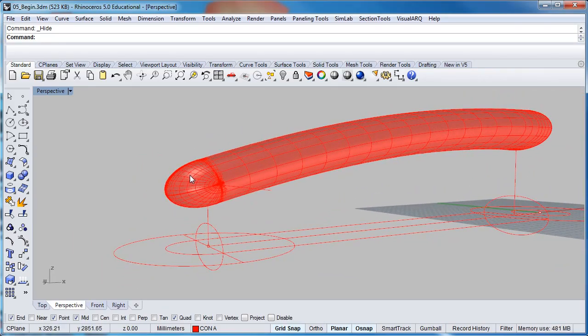So one of the things that we're going to explore during this session is we're going to use the revolve command in order to build it from first principles. And we're also going to learn how to import models into our project under construction, such that we can take details that we've already fabricated and conveniently place them as we require.